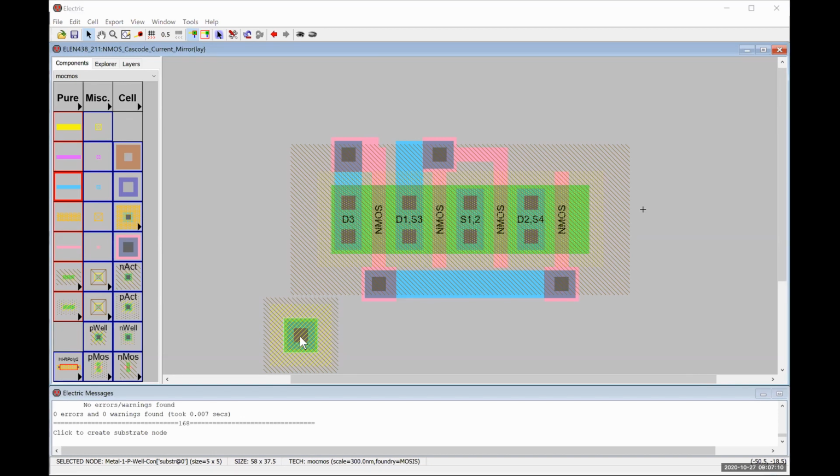And so what I'm going to do, let's see. Dr. Hartman, how are you going to get a source of 1 and 2 to ground? So that's what I'm about to figure out. I might need to make that metal run that connects the gate of M3 to M4, I might need to move it up a metal layer.